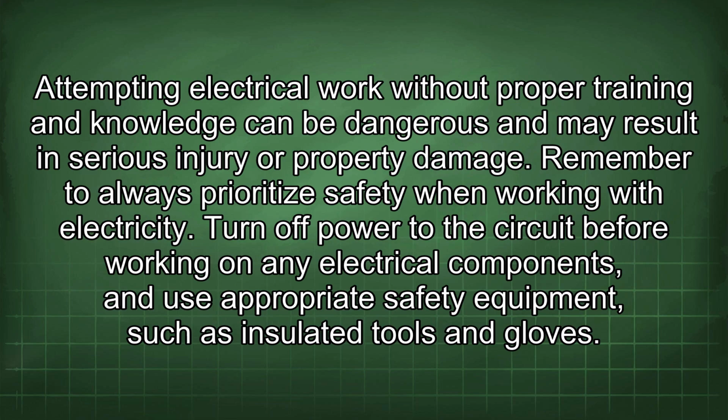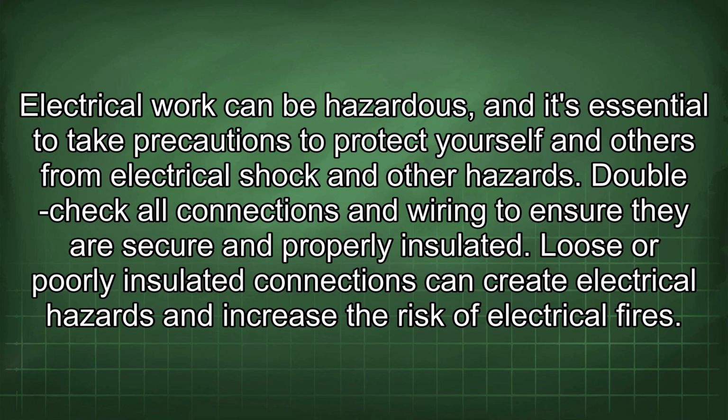Turn off power to the circuit before working on any electrical components, and use appropriate safety equipment such as insulated tools and gloves. Electrical work can be hazardous, and it's essential to take precautions to protect yourself and others from electrical shock and other hazards. Double-check all connections and wiring to ensure they are secure and properly insulated. Loose or poorly insulated connections can create electrical hazards and increase the risk of electrical fires.